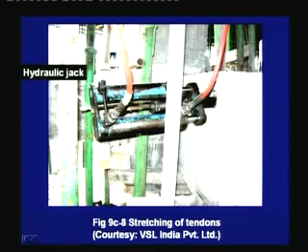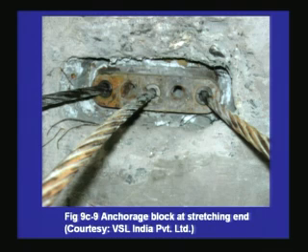Once the concrete is cast and it attains a desired strength, then the slab is post-tensioned by hydraulic jacks. Now, in this photograph you can see that a hydraulic jack has been placed at the side of the slab, and the tendons are being stretched by this jack to the required amount of prestressing force.